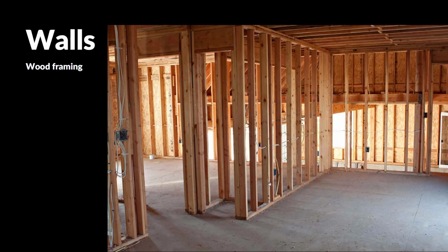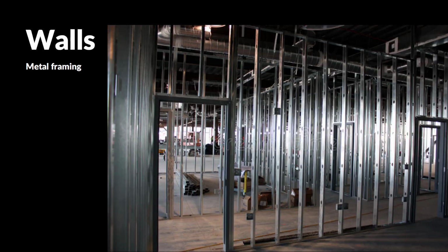So here's a photograph of a residence that's under construction. We can see the raw subfloor here. That's just plywood, 4x8 sheets of plywood. And then you can see, for example, everything that we just saw in that picture. We have that single stud, the floor plate running across, the 2x4 studs running vertical. We have the double top plate up here. And you'll also notice in here these wires that are running through, that's the electricity that's being run through the studs at this point.